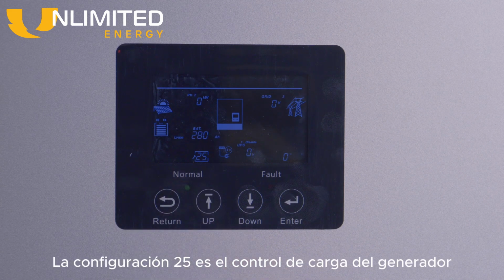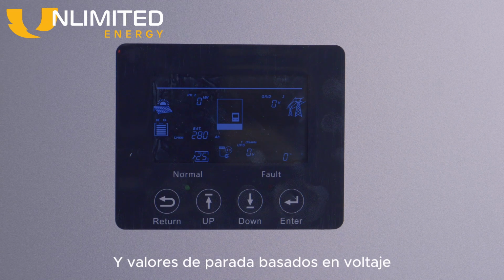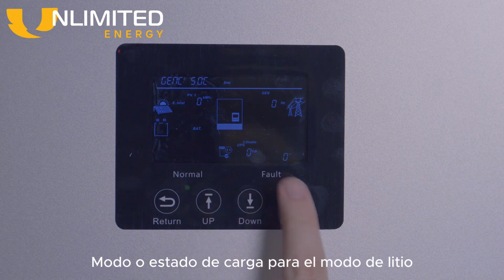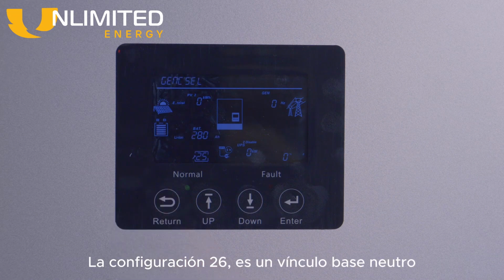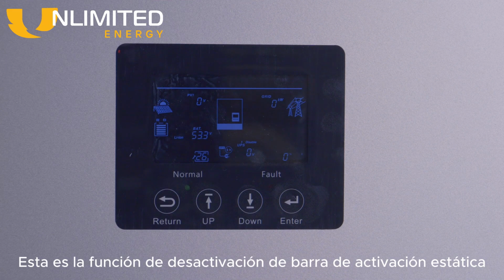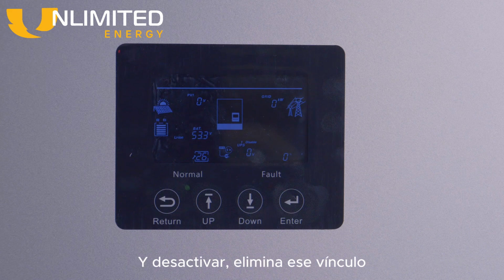Setting 25 is generator charge control. This is where you set up start and stop values based on voltage for lead-acid mode or state of charge for lithium mode. Setting 26 is neutral ground bond. This is the static enable/disable function where enable will allow the inverter to form the bond and disable removes that bond.